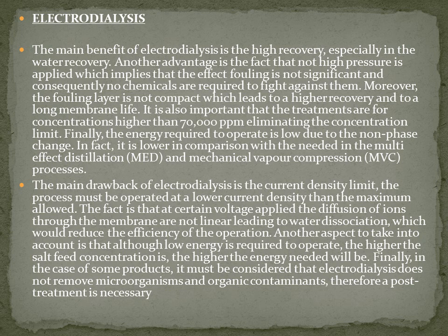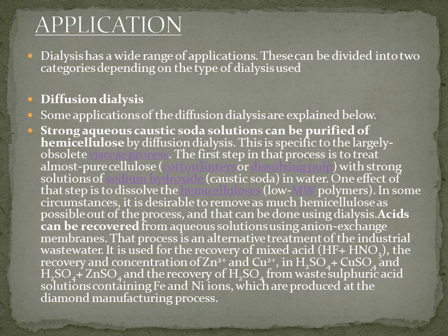Another aspect to take into account is that although low energy is required to operate, the higher the salt feed concentration is, the higher the energy needed will be. In the case of some products, it must be considered that electrodialysis does not remove microorganisms and organic contaminants, therefore a post-treatment is necessary. Applications of dialysis can be divided into two categories based on their type.